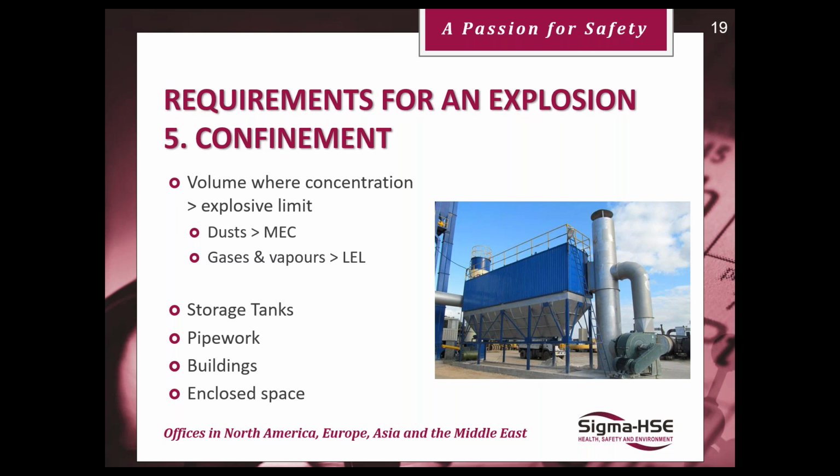So on the converse side, if we can ensure that our powders are well below the minimum explosive concentration, or our temperatures or vapor concentrations, due to extraction and ventilation that we install into our equipment, we can ensure that we keep below these concentration limits. And then we're safe. Simple as that, really.